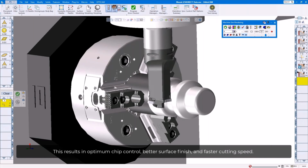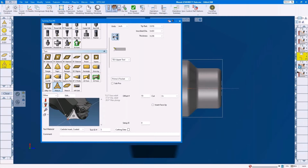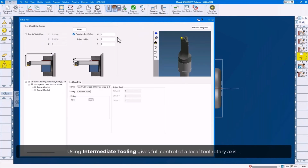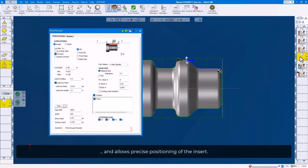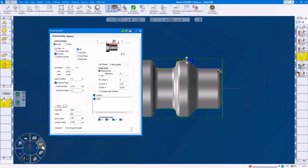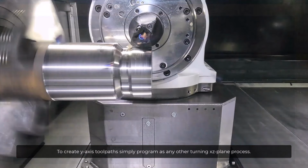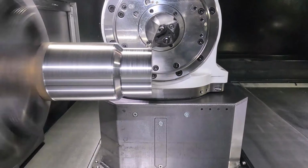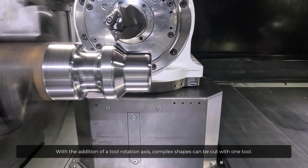And this continuous sweeping is we treat more like a B-axis turning if you've ever done that before, but instead of a B-axis, we're using that local tool axis. And right now, the only thing that's required is you have to set up a tool holder as intermediate tooling in the right coordinate system. And that's how you do it the same way in Gibbs. And then it just puts everything in the right coordinate system for you. So there's very little difference than just normal turning from that aspect.